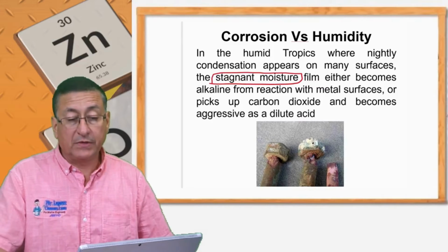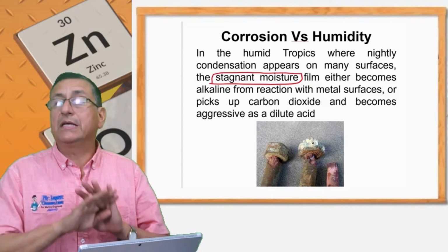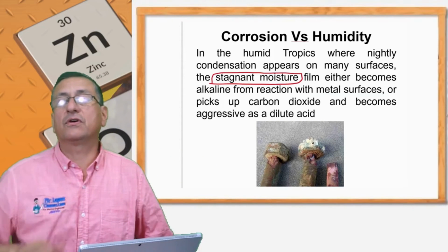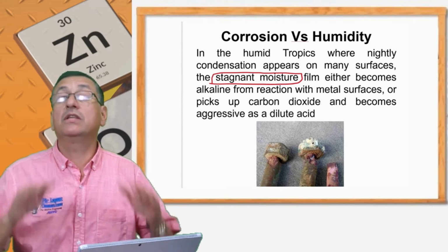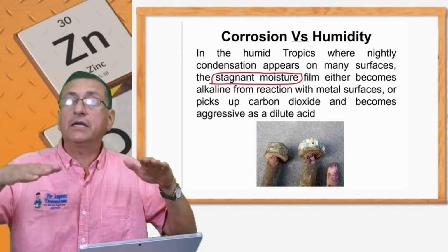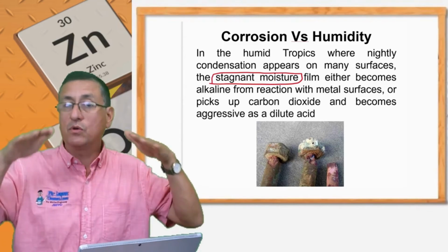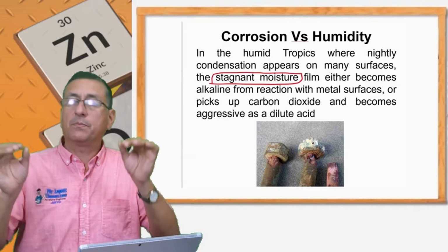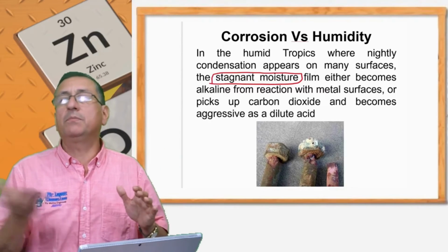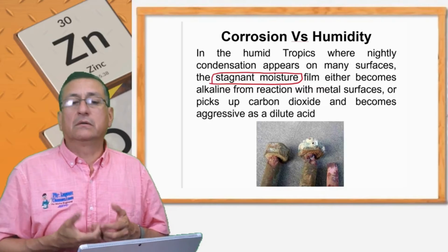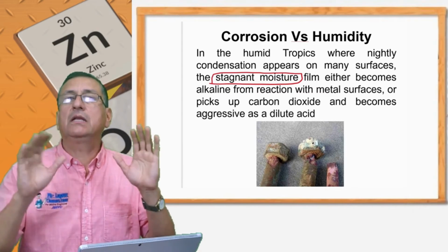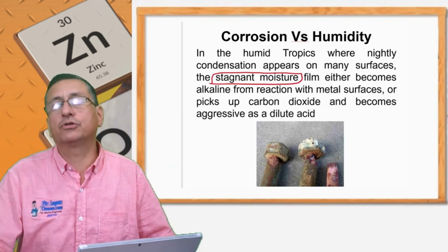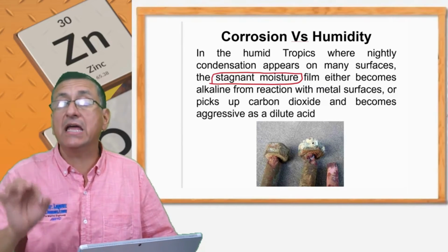It's simple. Once again, you need to eliminate the stagnant water, the water accumulated on the surface of the metals. You need to design the appropriate inclination of the fuel tanks, the water tanks, the water makers, and the air conditioning equipment, in order to keep the pans, the grills, everything dry. If everything is dry, you don't have corrosion. That's the secret. Keep everything dry.